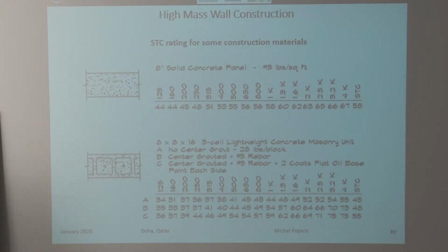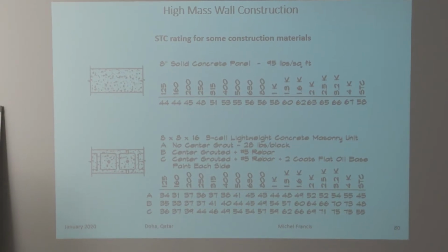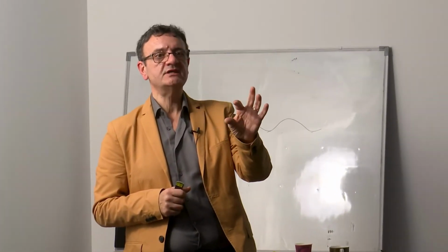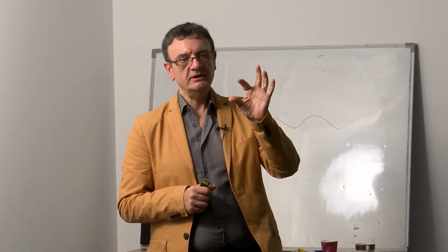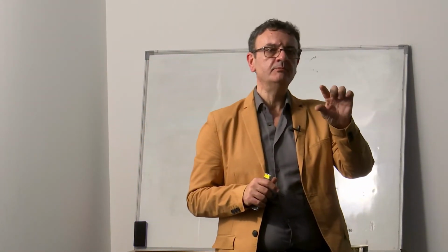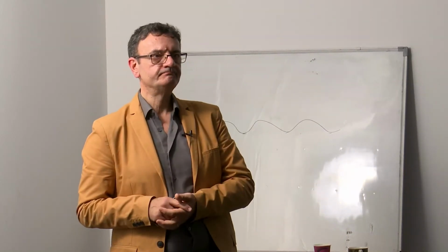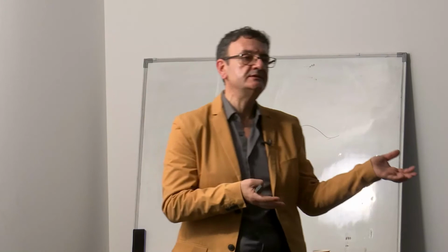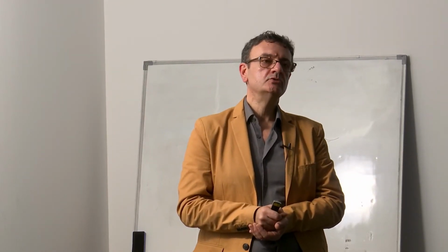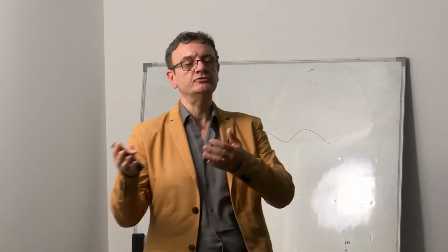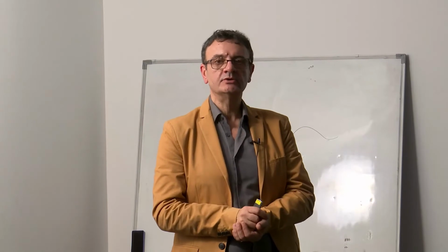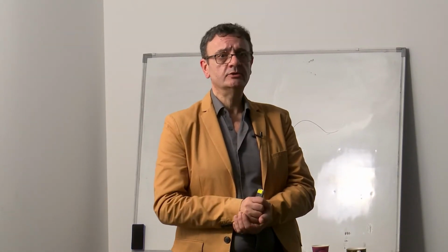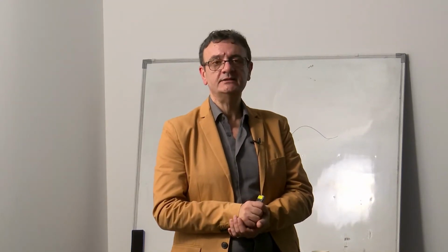So whenever someone asks you about the STC rating on the section shown in your catalog, tell them this STC is for this section. The more layers you add, that's going to improve. If you reduce from there, it's going to decrease, and I cannot tell you how much it's going to decrease. But that is the minimum I can claim for that assembly because it's shown here. That's it. If someone really wants more information, then you need to do an STC test in a lab. You have to take it to your local lab, or if you don't have a local one, do it in a lab elsewhere, and it should be recognized by your client at least, or your authority having jurisdiction, so that you can claim that test. Anyway, try to get away from there.